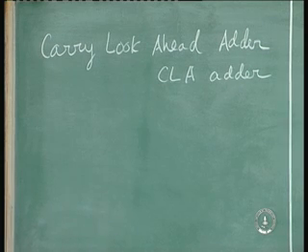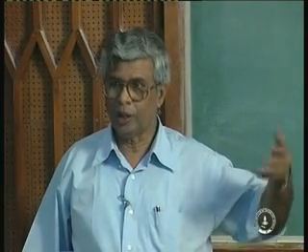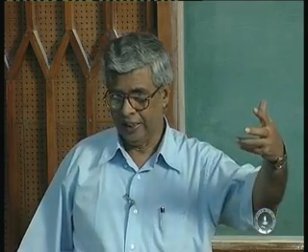As I said, can you look ahead? The carry of different stages can be looked ahead as soon as the bits are known. As soon as the bits are known, can you compute the carry ahead of time and then use it when it is required, a sort of prediction by computation in advance using extra logic. That is why I said extra logic can give you extra speed, and this technique is called carry look ahead for that reason. So we are going to have extra hardware which generates the carry for different stages, keeps it ready, and uses it when required.